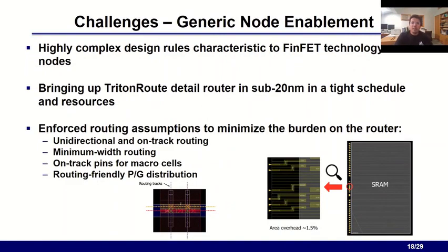The last challenge I would like to mention in this talk is related to routing. Detailed routing for FinFET technology nodes is a significant challenge. A routing tool must understand all the hundreds of complex design rules in order to properly route designs without violations. As internal design advisors, helping TritonRoute achieve zero DRVs with limited time and resources was a significant challenge. Following the generic node enablement methodology, we made and enforced assumptions in routing rules to minimize the required design rule support.